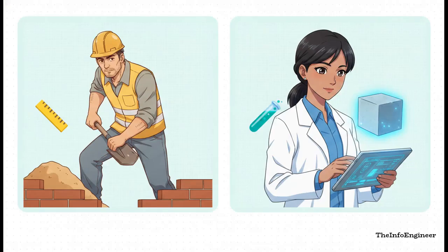Really, the fundamental difference here boils down to assumption versus guarantee. The nominal mix relies entirely on fixed volumetric proportions. You know the drill, that classic 1-2-4 ratio of cement, sand, and aggregate. It's super easy to use for a quick, small job because pretty much anyone with basic concrete experience can whip it up. But here's the catch. Its compressive strength is purely assumed. You're guessing.